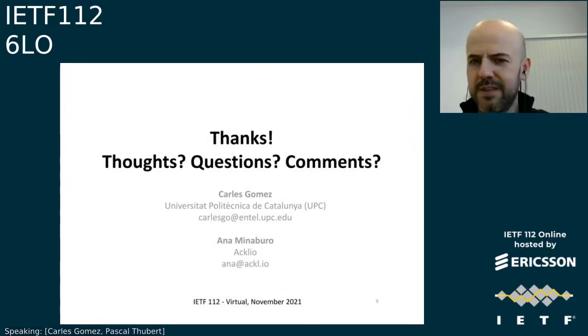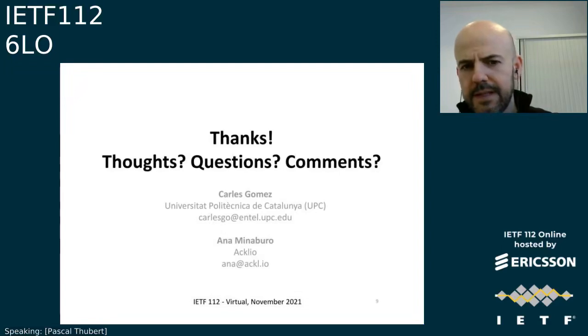Okay, then we'll, yeah. I mean, if you were talking about Bluetooth, we could say, hey, kind of easy, right? If you talk to the central device, then probably you can be asymmetrical. If you talk device to device, it would be symmetrical. Because you know who is your central device, but in 15.4, you don't know who that would be. Maybe we could just say symmetrical by default. Do we really need this optimization of being asymmetrical?